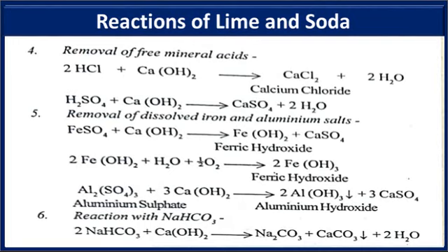Again, the next reaction is the reaction with sodium bicarbonate. If sodium bicarbonate is present in the water, it reacts with the lime and generates sodium carbonate, calcium carbonate and water. So sodium bicarbonate generates sodium carbonate, that means the soda.